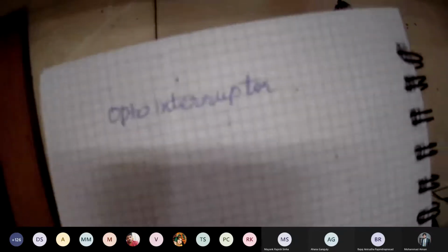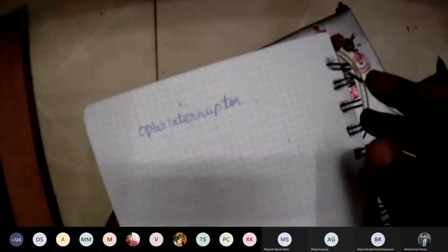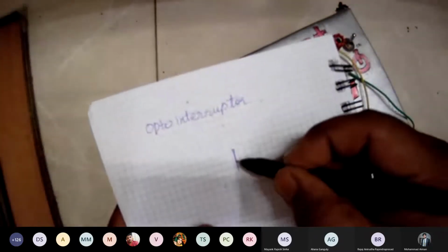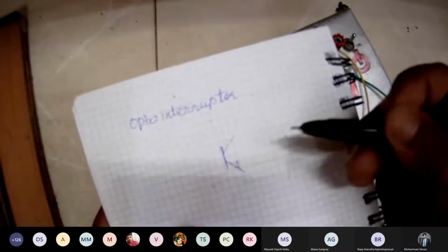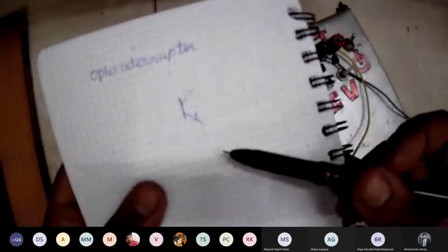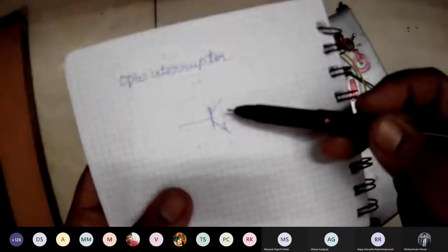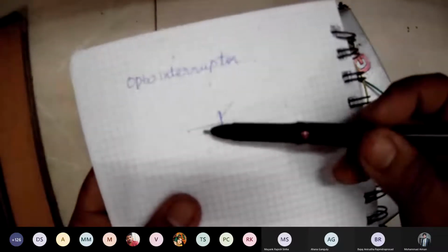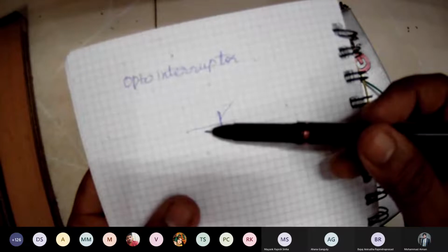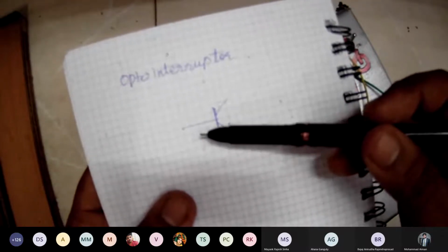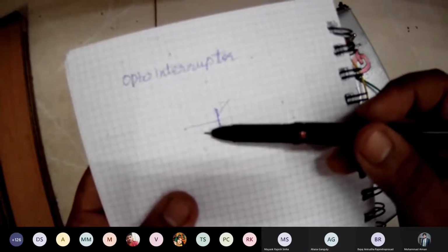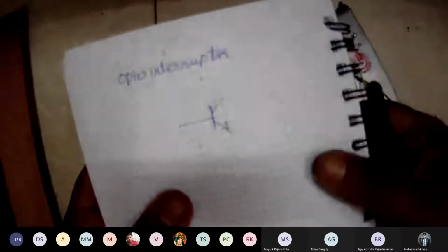So in the last class, we saw that if you want to achieve some kind of switching, you have the base of a transistor like this. In this case, it's an NPN transistor, and then you simply have to drive the base into saturation. You can drive the base into saturation with something which can source a very small amount of current as well. So something like an Arduino can also drive this requisite amount of current.